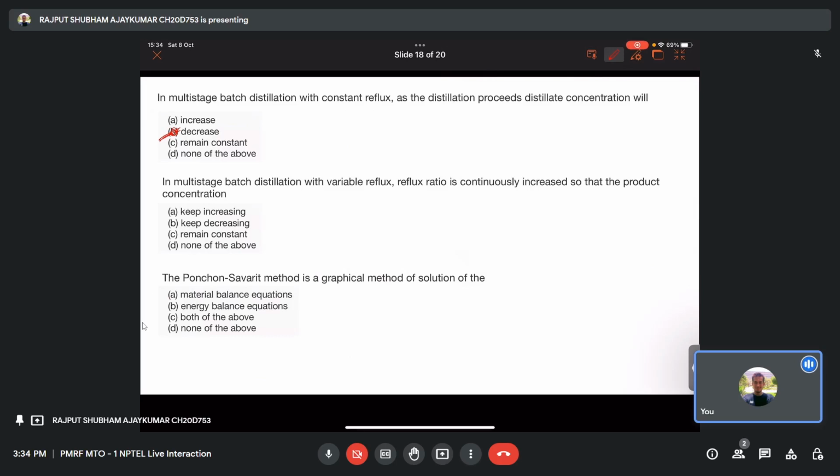And as soon as your feed is continuously pumped at a constant rate, the distillate concentration will remain constant, but it will decrease because the rectifying and the stripping sections will have to separate the gas and the liquid again and again. And because it's a steady state process, what we have to consider is the trace amount of impurities, as well as many other terms that we already discussed, like weeping, coning, dumping, flooding, which will happen at some point of time and will reduce the concentration of the distillate.